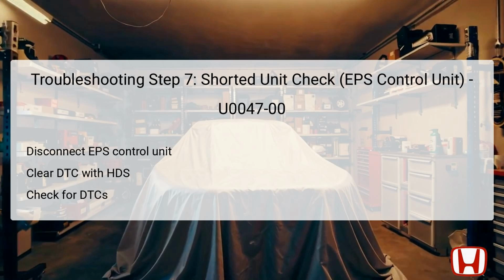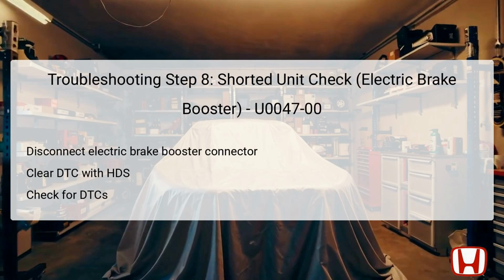As with previous steps, power the vehicle down, pause for 6 seconds, then reactivate, proceeding to check for error codes. If the DTC persists, further investigation into remaining systems and control units is warranted to locate the root of the communication failure. Moving on, we will investigate the electric brake booster as a potential source of DTC U0047-00. Initiate this step by ensuring the vehicle is in off mode.